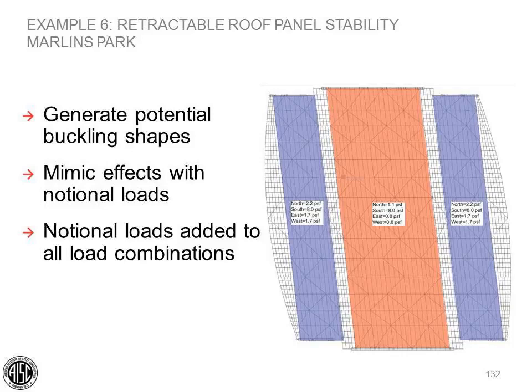And if you, say, take a simple column model and just displace it by the 0.002 or the h/500 and see the results there and then compare that to a notional load, you'll find that you can subtract that notional load out at the base of your column and end up with the same results. So it's usually a small load, so in our practice we typically just include it in there, but you don't have to. But again, that applies for the shears only. For the moments, you need to design for those moments.